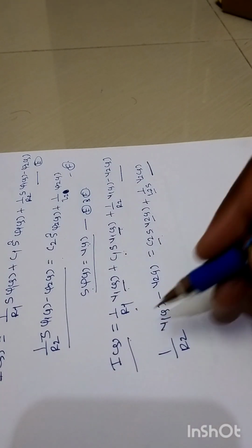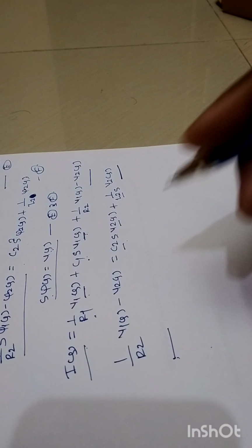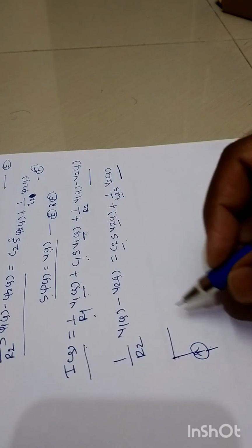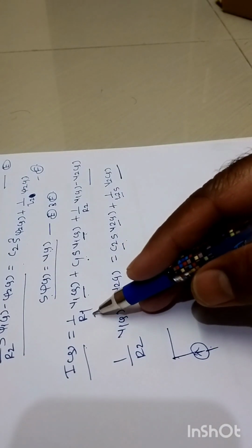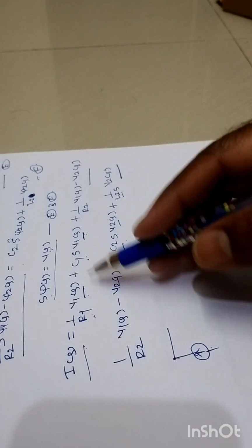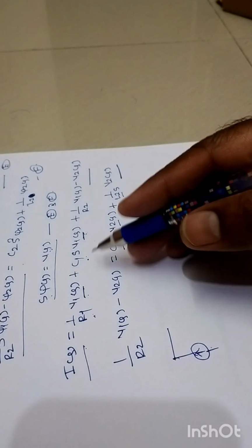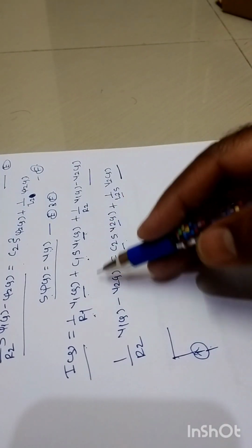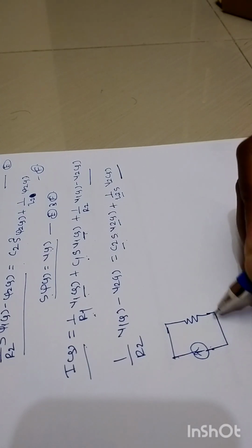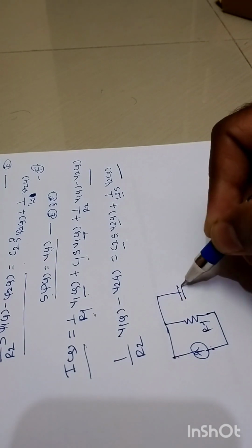As a result of doing this, the first component that we need to consider is this I. So basically I is nothing but what? This is the current, so denoted by this symbol I. Immediately after that, the coefficient of R1 and C1 is the same, that is nothing but V, means these two elements are connected in shunt form so that they are sharing the similar voltage. If they were sharing the similar current, these two elements would be connected in series form, but here they are sharing the similar voltage, means they are connected in shunt form. So this will be R1, and this is nothing but C1.